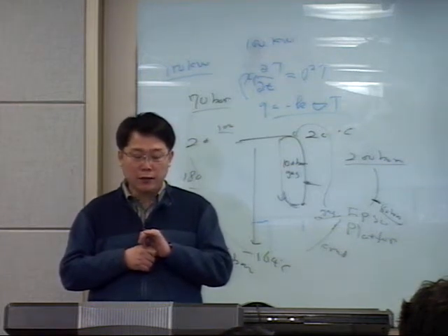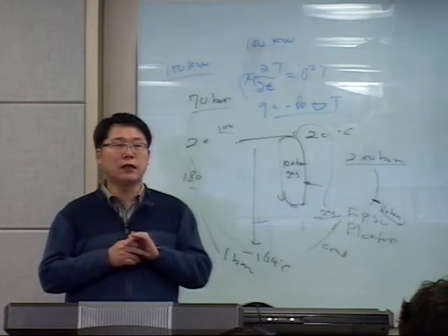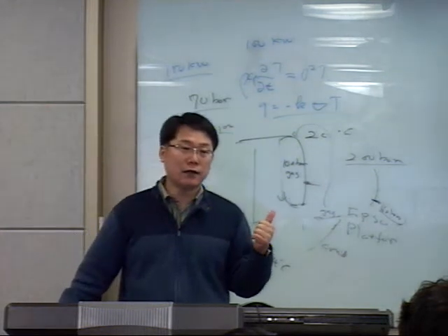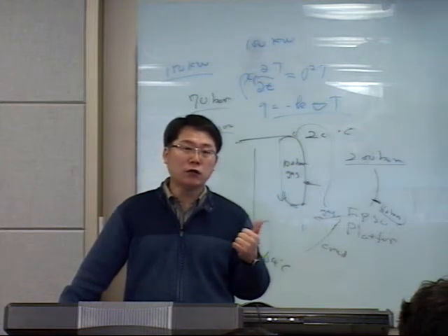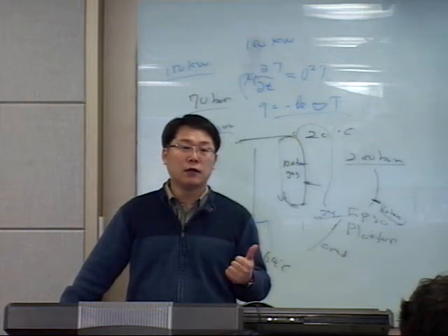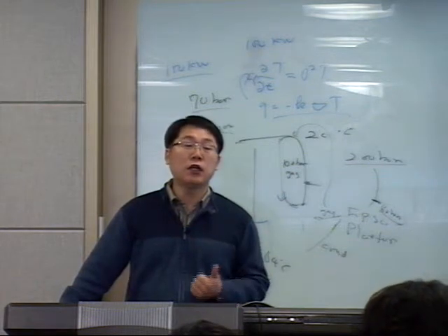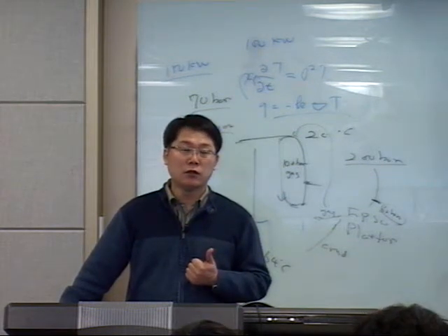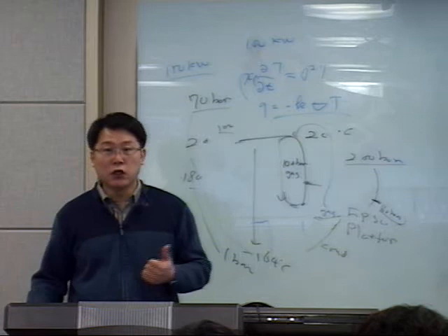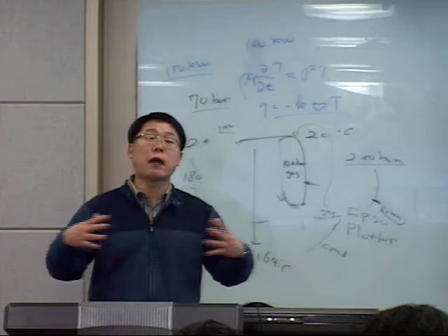Then, what is process engineering? The main concern of process engineering is first sizing. They want to decide the capacity of the compressor, the heating or cooling capacity of the heat exchanger. So, in other words, if you are a mechanical engineer, you need information about the boundary condition, including the capacity.